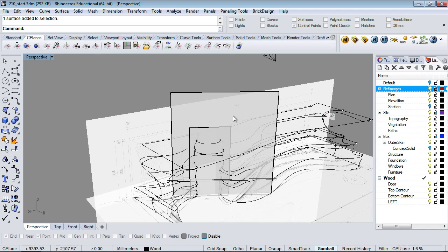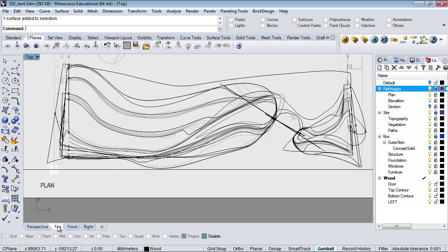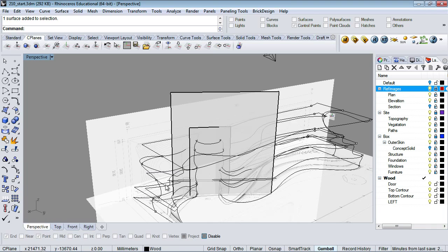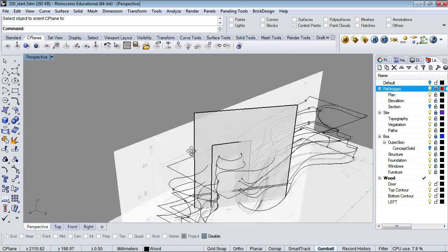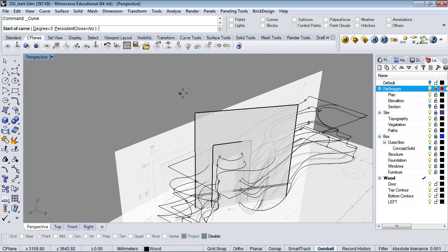You just move around, and I get it set in plan view, okay? In the top view, I get them set, and then I move into the perspective, tell it to orient the construction plane, and then I draw in perspective, okay? And turn off your object snaps when you're doing that, and just snap to the intersections, okay? And then that way you can really control what it's going to look like in section, and you have a conception of the overall form. And then once we get that together, we can sweep those pieces. So I'm just going to draw some quick geometry over here.